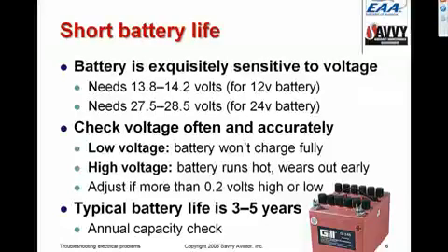By measuring the ampere-hour capacity of the battery that way and comparing it to the ampere-hour spec for the battery, we know when it's time to replace the battery. I think Gill recommends replacing it when the capacity deteriorates to 80% of spec, and Concord recommends 85% of spec. So doing an annual capacity check is a good idea, because it gives you an objective way of determining when to replace the battery and not risk getting stranded someplace.